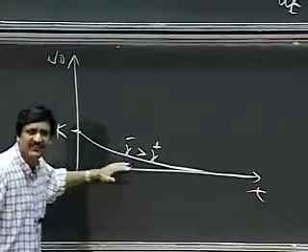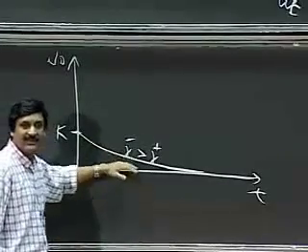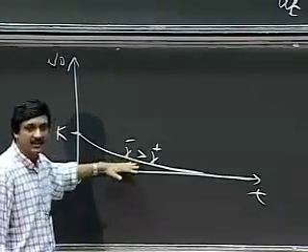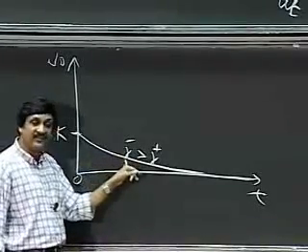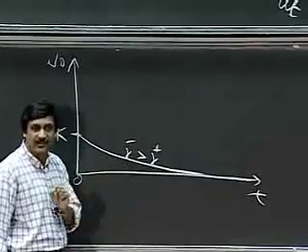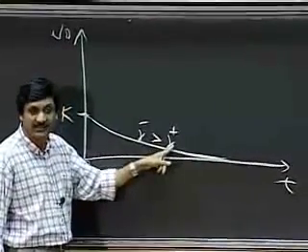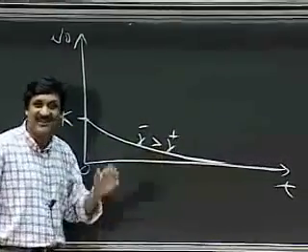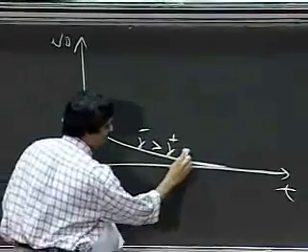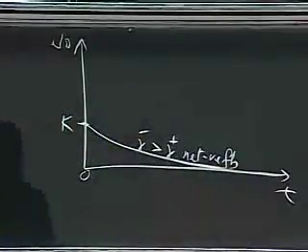So intuitively, what am I saying here? All the gammas and other pieces of crapola aside, what am I really saying here in English? What I'm saying is that if the portion of the output fed to the negative input is greater than that fed to the positive input, then I have net negative feedback.